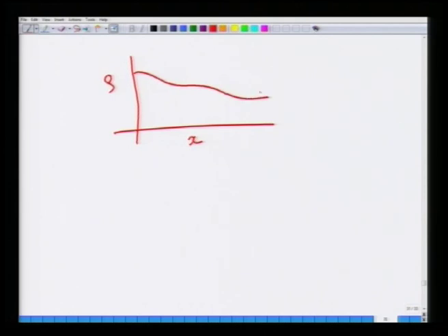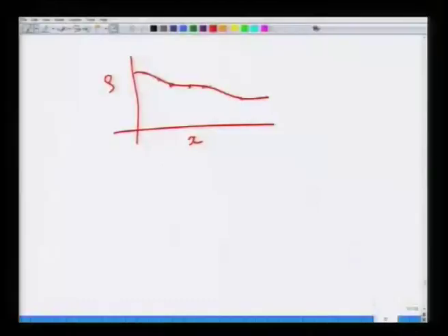So, density could vary smoothly as a function of x, where at each and every point you have taken this probe and measured the density by measuring the mass, and regardless of the size of the probe volume, you will get a unique value in your experiment. So, this is the notion in which density, for example, is defined in a continuum approximation.